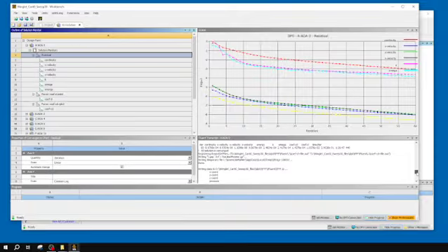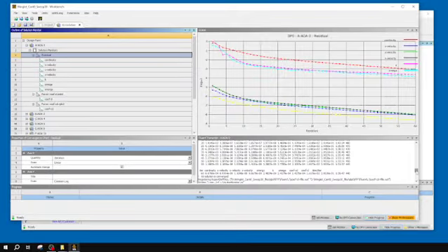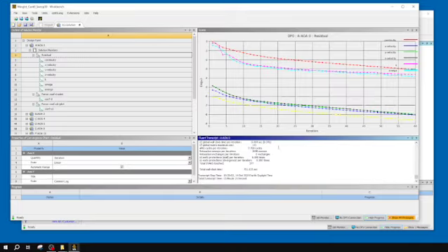And you can see here, lift's barely changing, drag's barely changing. So it's basically found the steady state solution that it was looking for. Sometimes it only takes 60, right? I had a pretty well-defined mesh and well-initialized mesh for this case, so that helps it take less. Also, 0 is a pretty simple one to calculate.